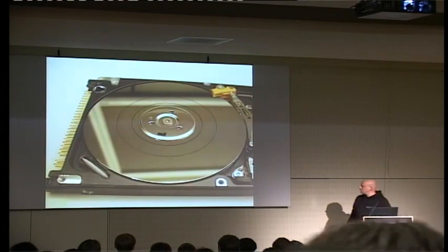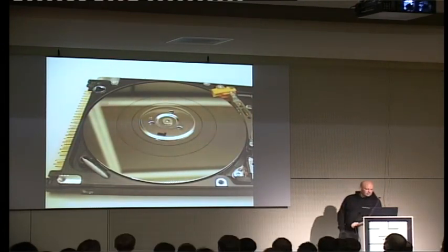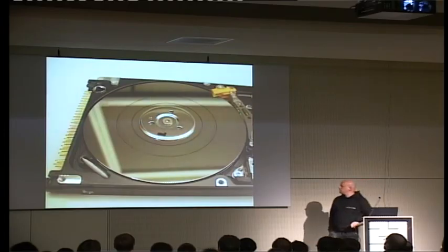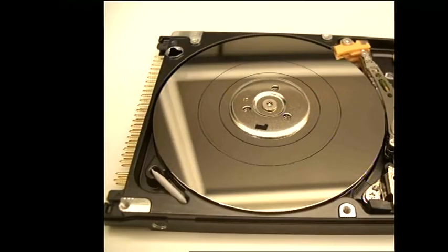this is a circular crash on a hard drive with glass platters. Unfortunately, it doesn't look so bad, but this one is fatal. And there's two reasons for it. One reason is the crash is in the area where the hard drive specific firmware parameters are, so you can't read them anymore. And the second is, maybe, I'm not sure if you can see it correctly on the photograph, but these are glass platters.